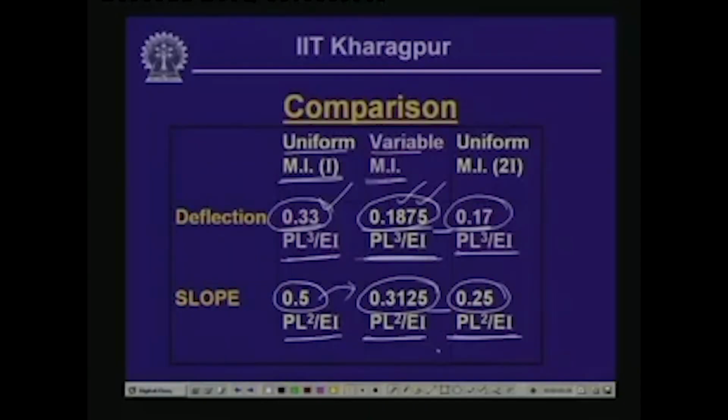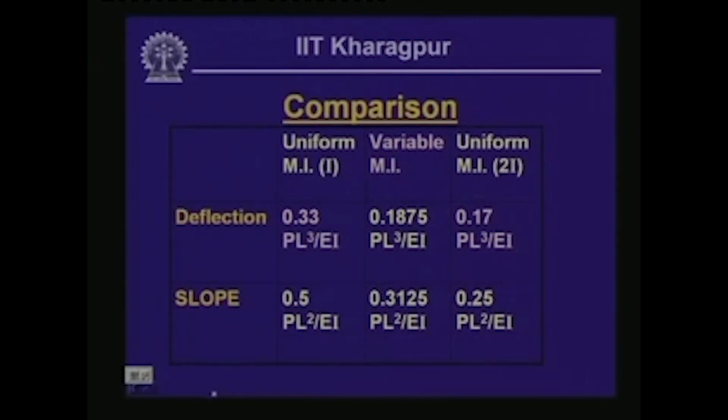Naturally, we have not used the material over the entire length of the beam, thereby we could make some economy in the selection of the section, and so we could make a trade off between the reduction in deflection and less usage of material between the two extreme cases. So, many times we employ this situation in design, so that we can reduce the deflection and at the same time economize on the sections which we use.